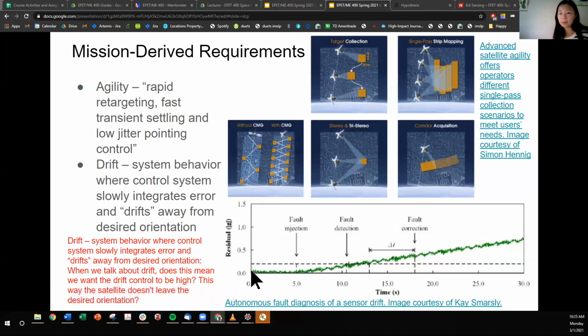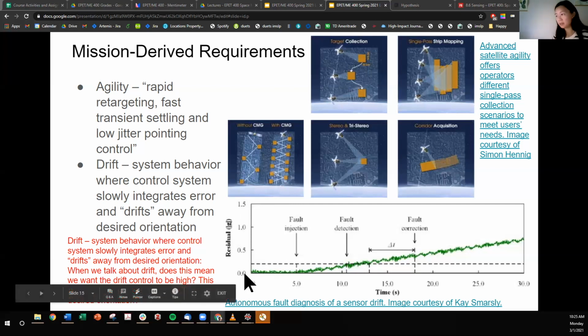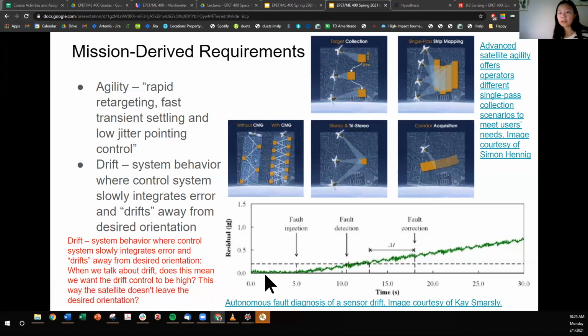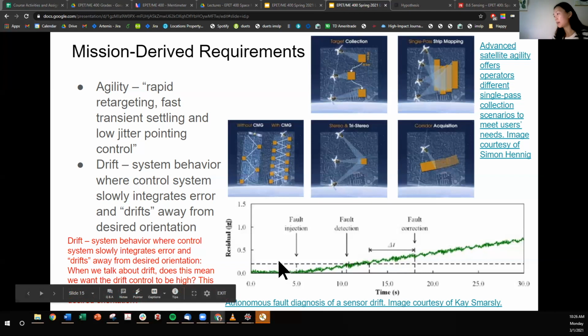A gyroscope within IMUs can cause the attitude estimate to drift if instead of measuring 0, like the spacecraft is assuming, you measure a tiny non-zero angular rate. If you measure this bias and you integrate it over time, then you're accumulating a non-zero angular attitude estimate over time.